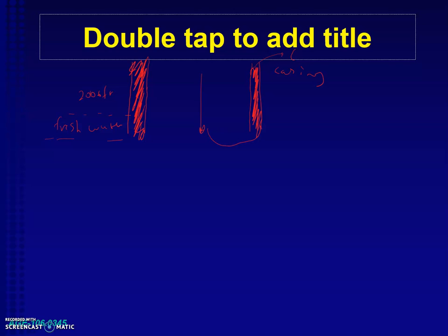So you have a piece of pipe here, which basically prevents the communication between your wellbore and all other formations there. This is called casing. Casing is beneficial in many ways. One is protecting the formations underground. It helps the integrity of the wellbore. It prevents the caving of these formations. As you go deeper, you may hit some formations that are unconsolidated and they may cave into the wellbore. So casing basically prevents these things from happening, so it improves the well integrity.